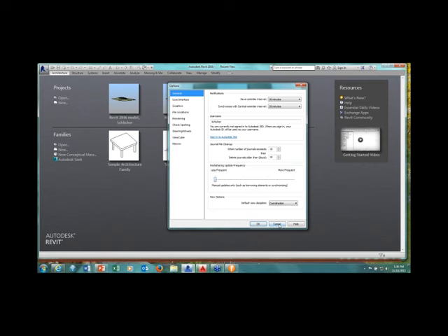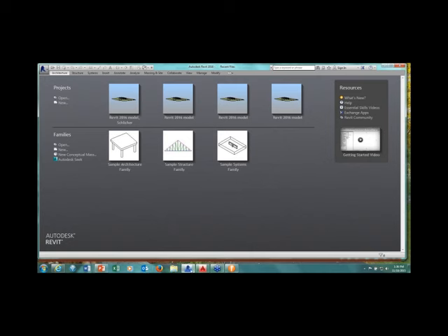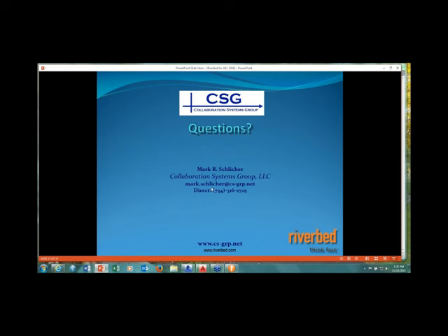The big thing that we find, though, is as I mentioned before, it's those attachments. So being very disciplined about where you're making those attachments. I always say a good rule of thumb or a good best practice is to make your attachments from the server on which the Revit model resides. And if you do that, then anyone who's accessing that Revit model, of course, will have access to all of those attachments. And not doing so, you won't see it necessarily in the open times, but when you do a sync to central, that's when you'll get 20 to 30-minute wait times.